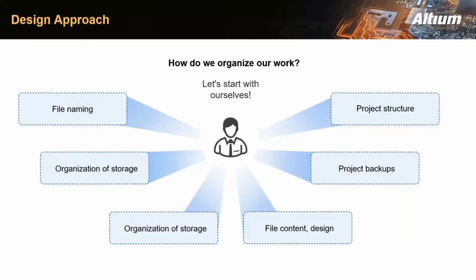Where and how do we store our projects and their associated files? Do you want to host it locally, online, or both? What file structure should each of our designs consist of? Schematic, PCB file, Draftsman documents, do we need to include technical documents, and so on? Do we know what kind of output files we need, and are there any customized output job files? And finally, do we back up our projects, just in case?